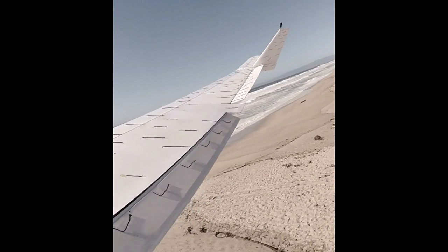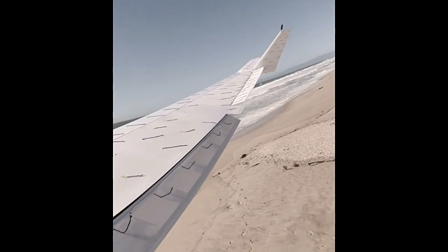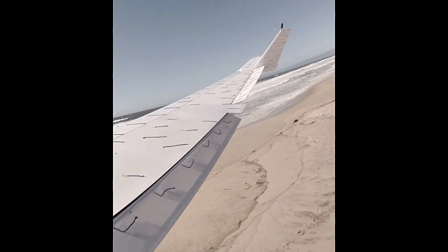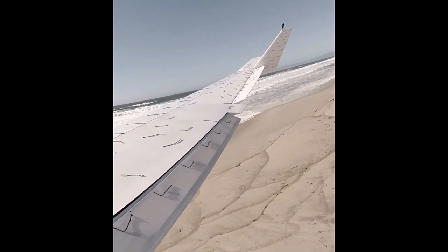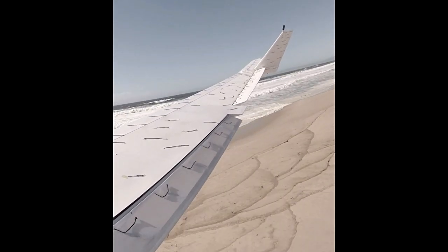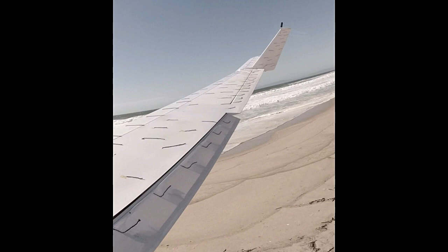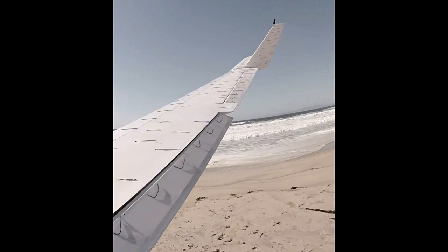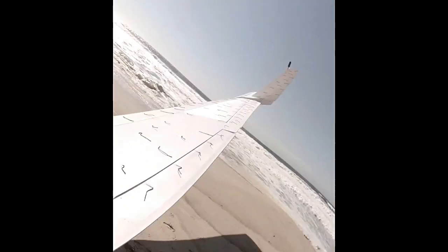Just really messy, nasty flow on the whole thing. So I'm probably only flying maybe 25 miles an hour here, maybe 28. Reynolds number is probably around 600,000 out on that elevon. And it's just stalls coming and going as I try to get it through the turn, because I'm trying to hold minimum speed. I'm trying to keep from careening into the sand at 40 miles an hour or something like that. That'd be bad. And I just did not have enough elevator to get the nose back up in time.